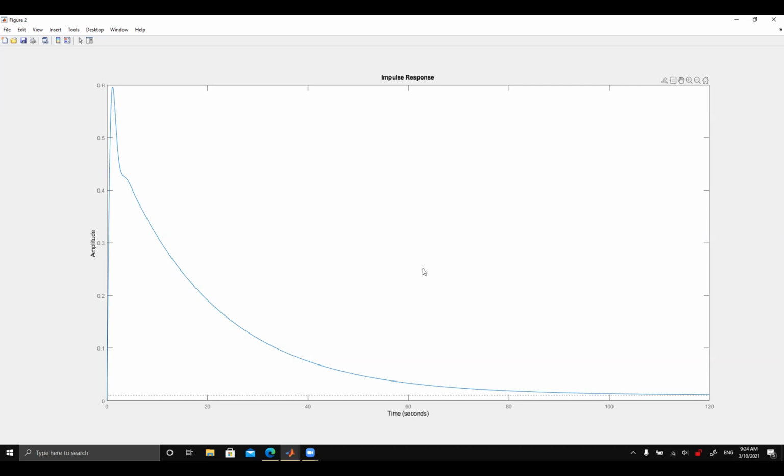Okay, so when we added the lag compensator, the pole and the zero that we added are very close to the origin, right? Which means that they do what? They dominate the response of the system, right? If you have a pole that is very close to the origin, it will have a very small decay rate, and so it will persist forever. That's why we see this steady state response. It's going to take a long time to settle down.